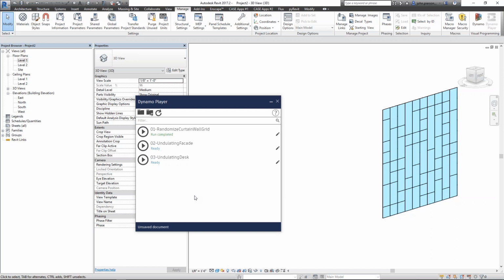We actually have a client who does facades, and they do mullions, transoms, and all this stuff for these cool curtain wall systems. They used structural framing for the transoms and mullions, and for the actual vertical members, they used columns. So we were placing structural elements with Dynamo based on these grid lines that were drawn with reference planes. The architect gave them constraints. We selected them all and pressed run, and it was pretty fun.